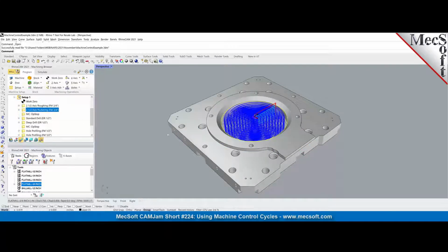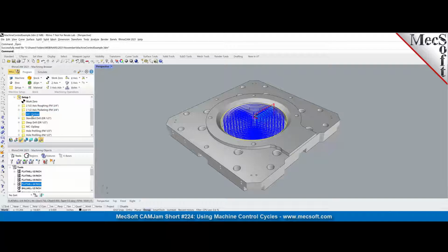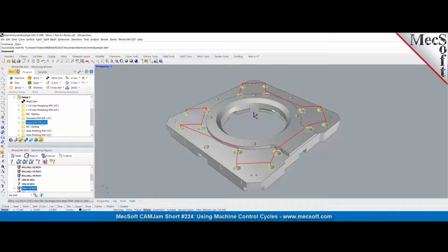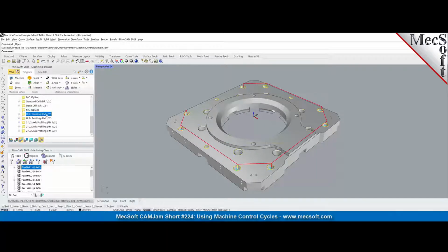And then to introduce the actual manual tool change, we have introduced a machine control operation. Then the tool is changed, and then we have the 1/2-inch drill to do the drilling operation. And once the drilling operations are done, we create another op stop operation, and then go into the final tool, which is a 1/2-inch flat end mill to do all the other operations.